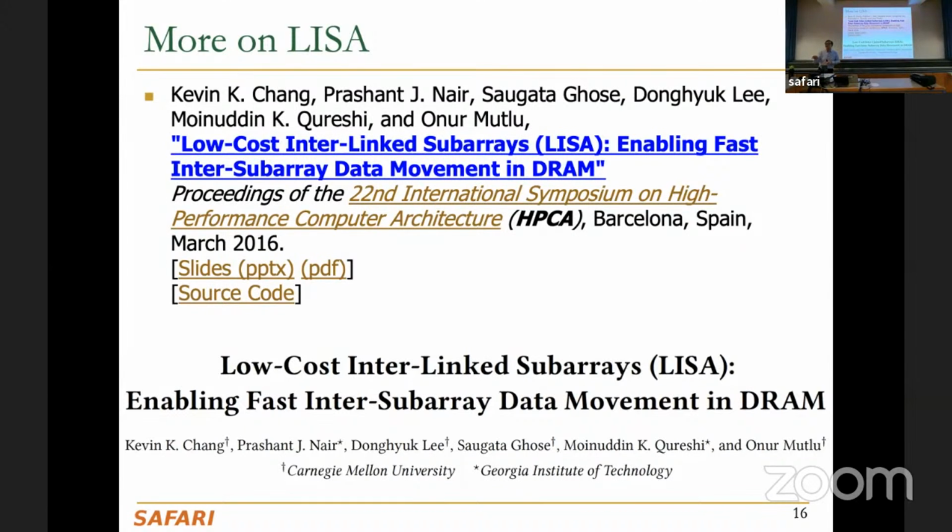We're going to cover interconnects in the later part of this lecture. You will see that all of the design space of interconnects applies over there. So you could have a simple bus, but that's not a good idea in general. You could have a ring, for example, which is relatively low cost, or you could have dynamically switched routers on chip. That clearly increases the cost. So you need some sort of protocol in the end. But the complexity of the interconnect and the protocol depends on how much cost you can pay.